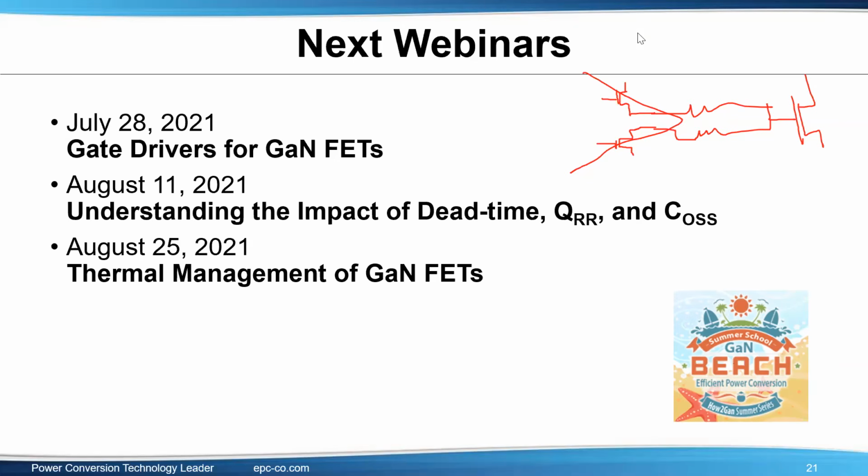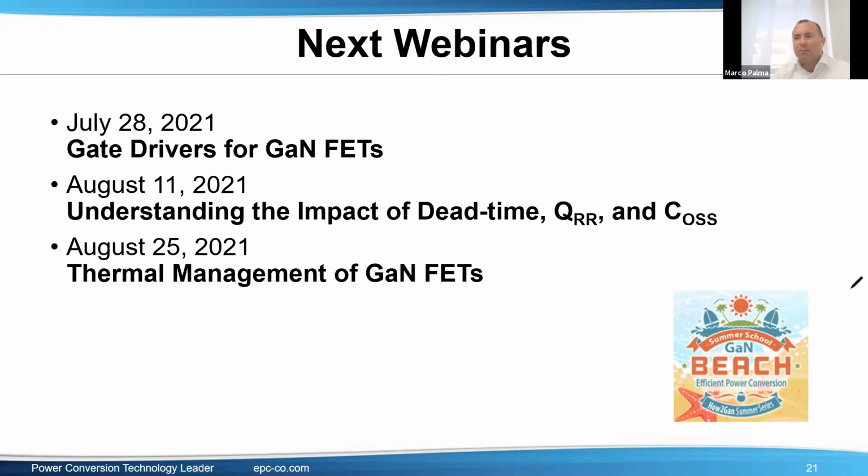What about putting FETs on both sides? I don't think it helps, because if you put FETs on both sides, first of all, you also have a thermal problem, because how are you going to remove the heat? The EPC GaNFETs are in chip scale package, and they are very efficient if you are able to remove the heat from the top.